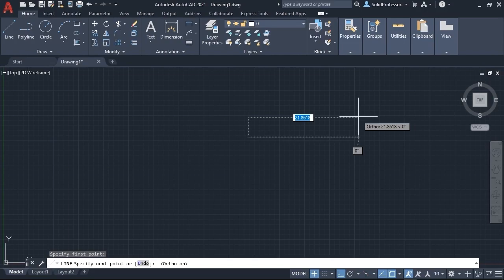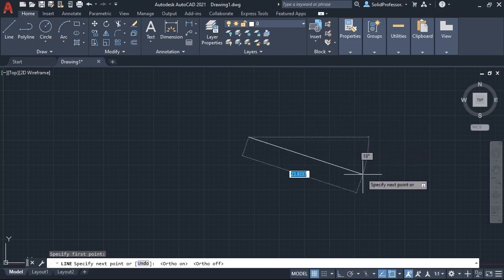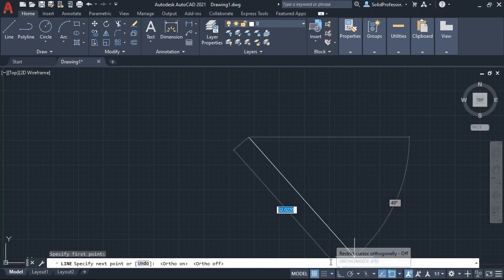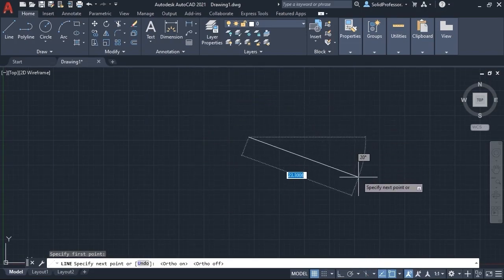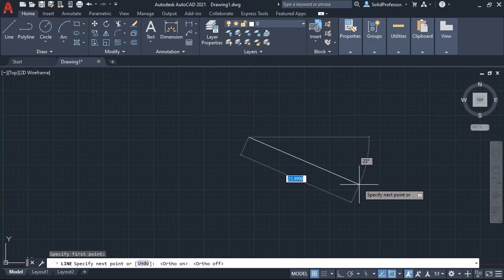I'll disable OrthoMode by pressing the F8 key, a hotkey listed if you hover over the settings icon, and I'm back to the normal full range of motion. This quick toggle can be a huge help when freehanding quickly if you're placing vertical or horizontal points.